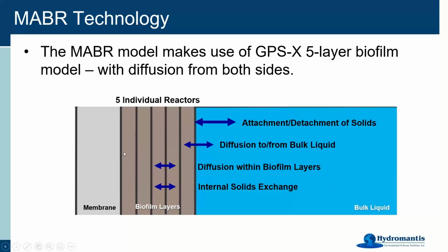But in general, these 5 reactors are modeled with the biological models that we have in exactly the same way that we would do any of our other biofilm. And in fact, it is the same way we do the liquid stuff too, because basically we're using our Mantis 2 model or whatever model you have picked to model the biological equations in these reactors. There's not anything different about the biological part of the model. It's just we're operating at much higher concentrations, and then we have these diffusion terms and attachment and detachment things thrown in there on top.